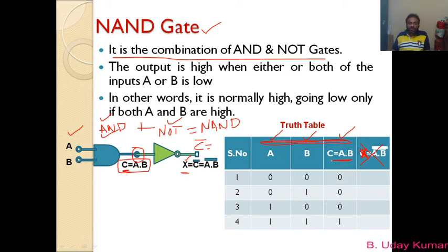Now I know the values of C, that means the voltage values that you get at the output of the AND gate, which we have found based on the different combinations of inputs. But now I want to find the output of the NAND gate. What do I have here? I have a dot b. Just find a dot b bar. Whatever values you get here, just write the inverse values, so you automatically get the output of the NAND gate. I hope it is clear.